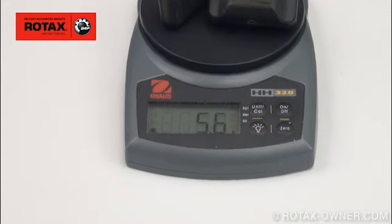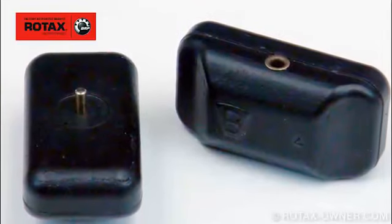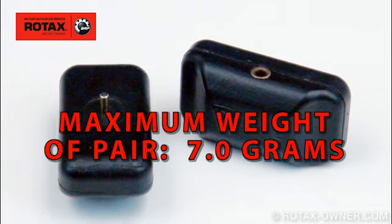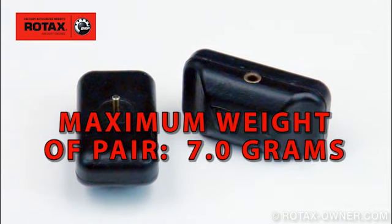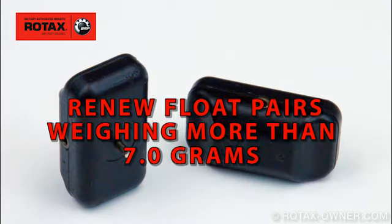The results of the measurement must be documented in the maintenance records. The maximum allowable weight of both floats together is 7.0 grams. The floats must be weighed in pairs, and floats are only available in pairs. Renew all floats which exceed the maximum weight.